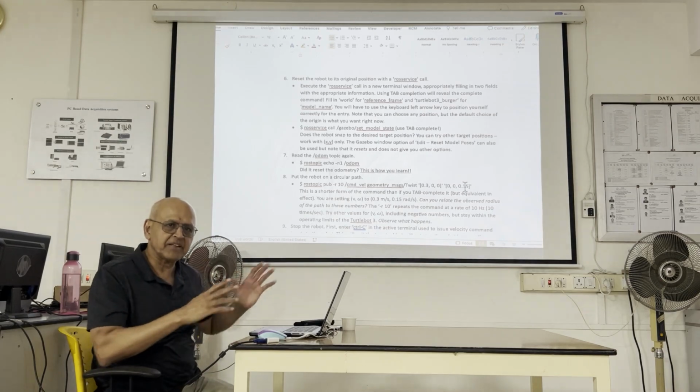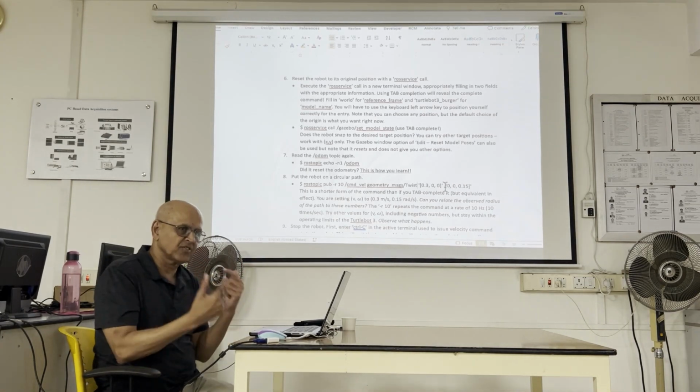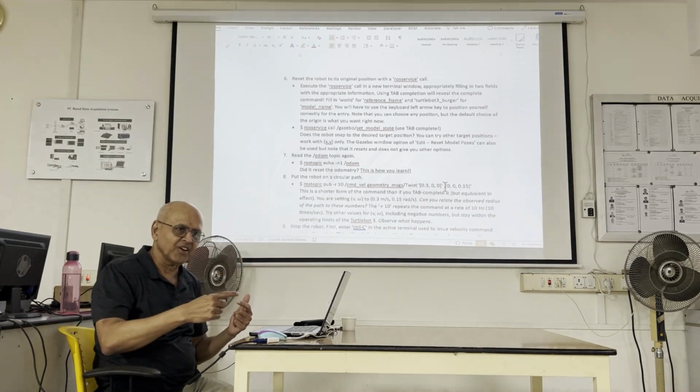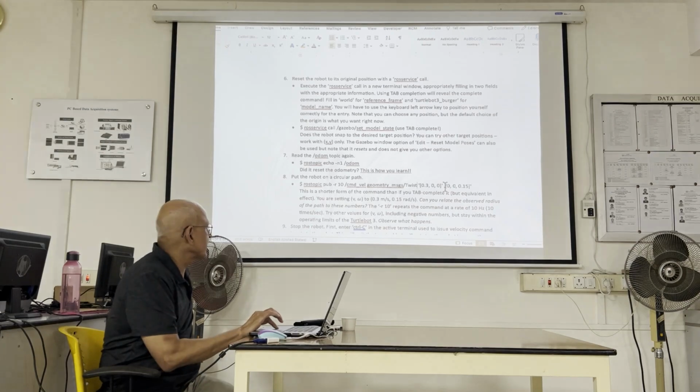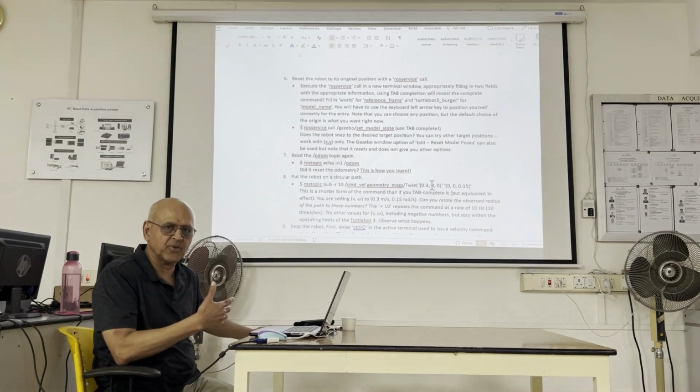Of course, all that depends on this command working. So first thing is, you run this command and get it working. And it'll go in a circle, you know? Why is it going in a circle? Because this is the forward velocity, 0.3. No side velocity, right? You can't give this robot a side velocity. It's not capable of moving sideways.